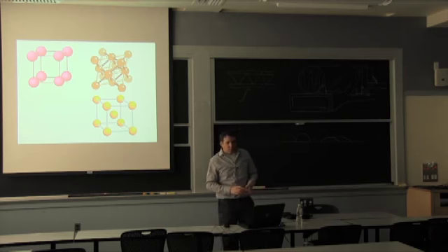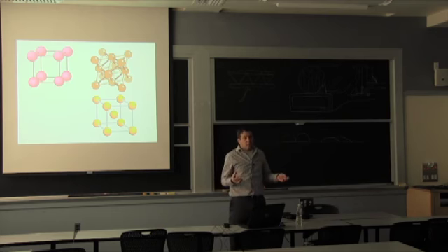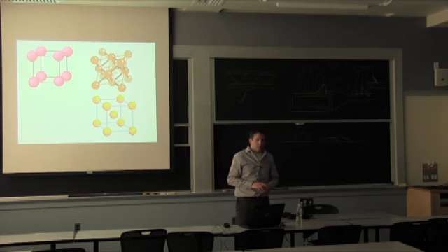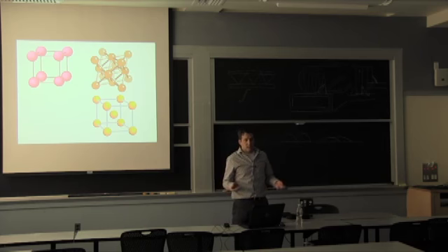It's not something, again, that's really stable. So when you get it from quenching, if you heat it back up, now you can get some different transformation to happen. And that's really something that's very particular to steel. It's not particular to steel that quenching it will make a different structure. What's particular to steel is how it's strengthening it. And not only strengthening it, there's a volume increase that's associated with that transformation.